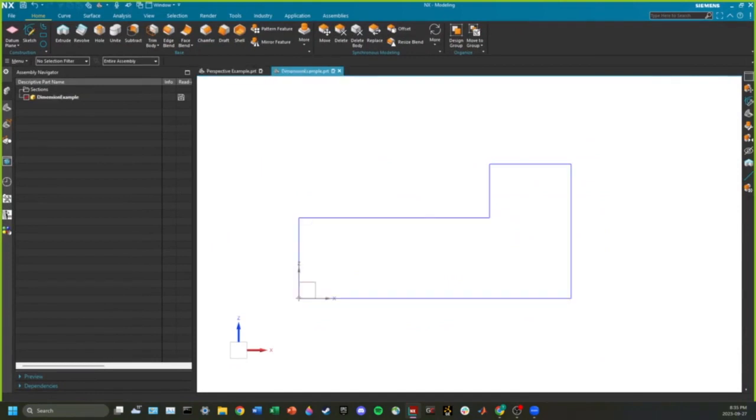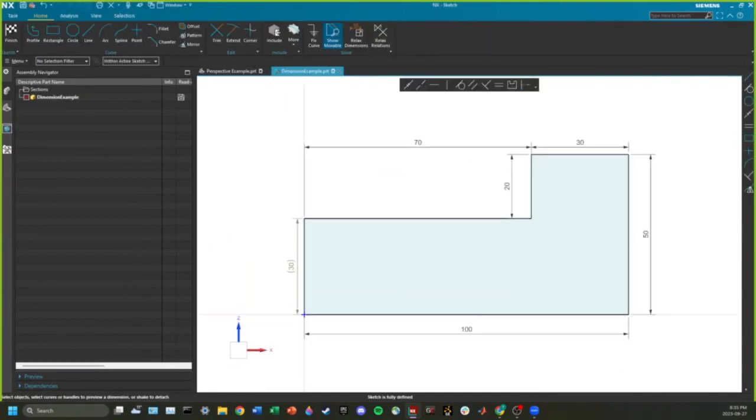Right here, let's go into it. So this is what, oops, sorry. On the presentation, that's what it looks like in SOLIDWORKS. This is what it looks like in NX. The origin now is that blue plus sign. And you can see the dotted lines being your axes, which in this case are X and Z. So we're looking at it from the front view because Z is vertical.